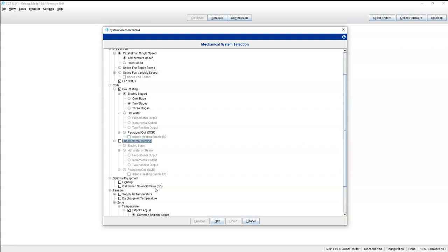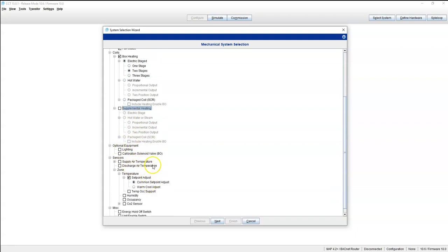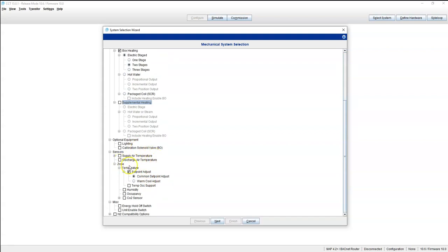So we put a solenoid valve between the unit and the velocity pressure tube, which would close that high pressure all the way off, showing 0 pressure without jacking with the damper at all. The damper is just going to lock in place while it does this little calibration every 14 days, and it goes on. Not too often. I've actually never seen this. Johnson has it in here, but I've never dealt with this.